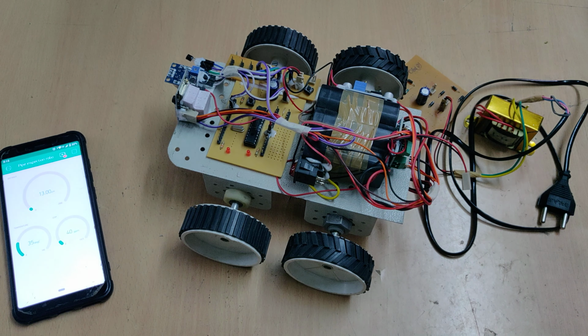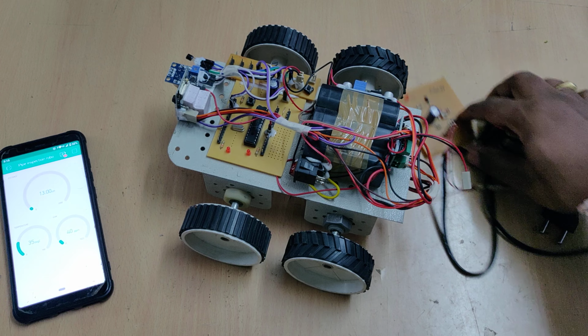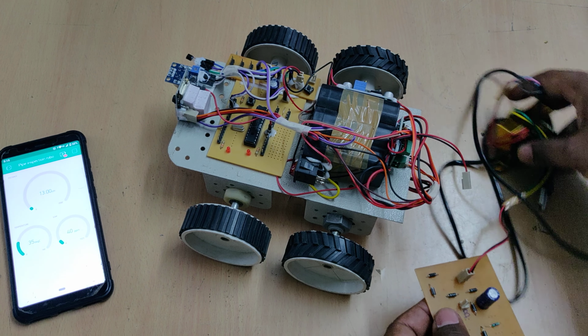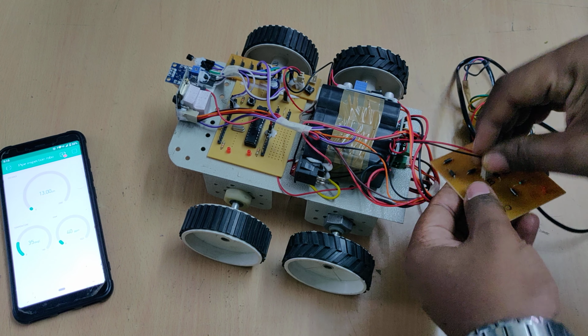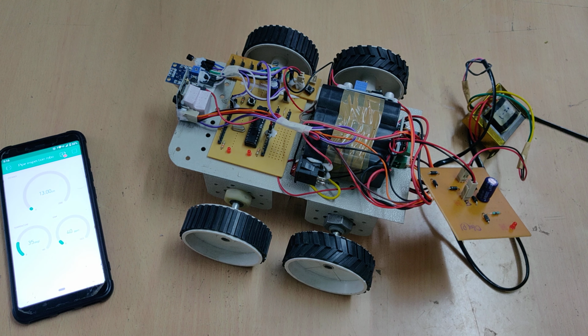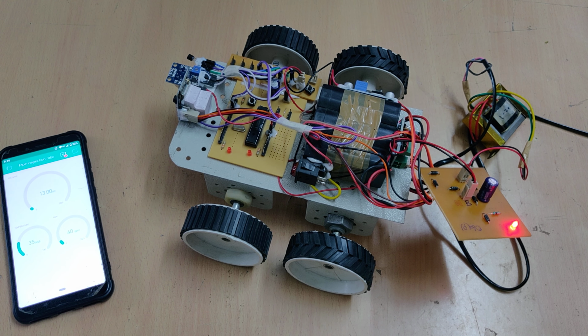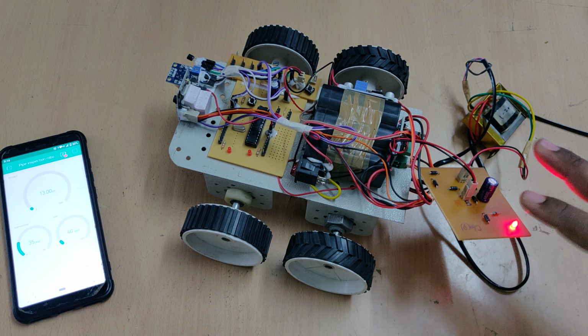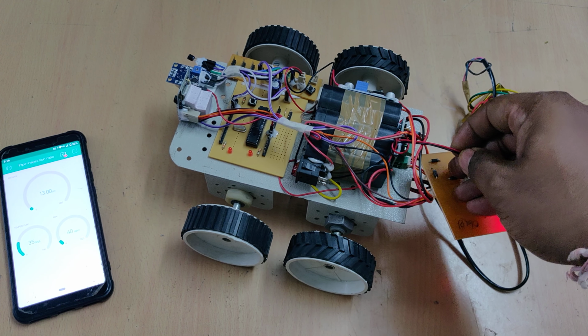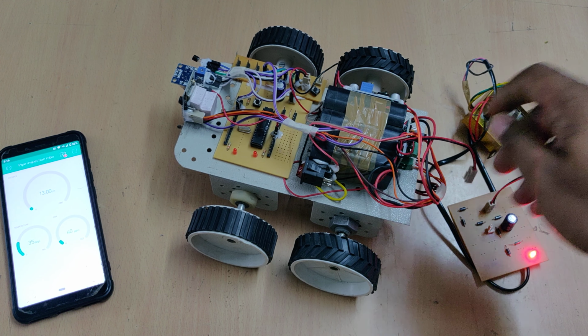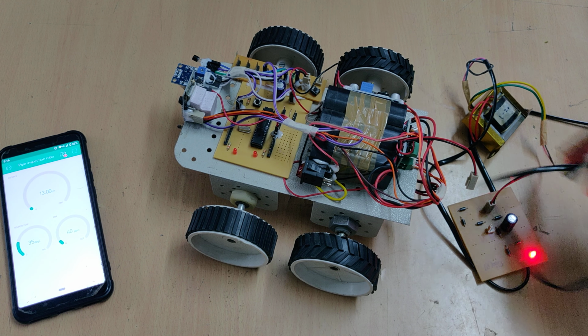As we are using a 12 volt 1 amp rechargeable battery, in order to recharge it, a charger is provided. We need to connect the battery to the battery slot over here, and then give the 230 volt input to the transformer. Then there is a light indication on the charging circuit. It will take a maximum of 8 to 10 hours to be fully charged, so till that time you should keep it on charging. Once the time completes, you can disconnect the charger, switch off the power supply to the charger, and keep it aside.